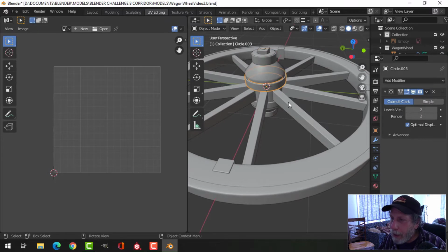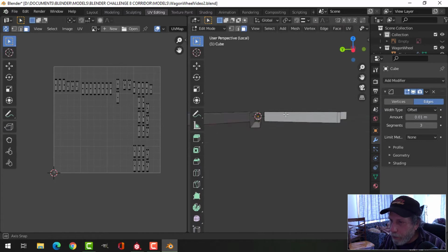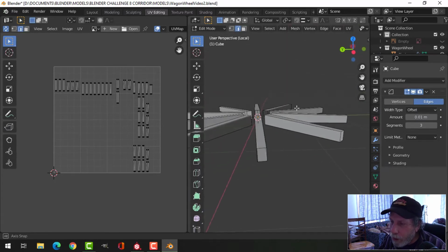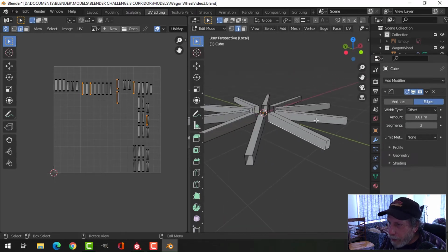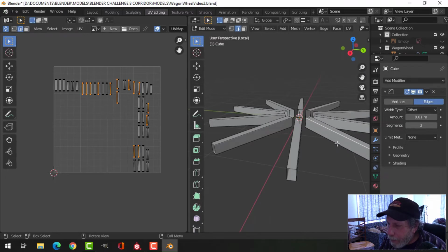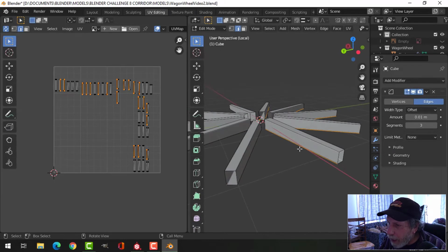Maybe the metal is okay. Let's just come into this stuff and see what we can do. What if we were to come in, and because there's nothing on the ends, if I want to unwrap this like it's a present, like this is wrapping paper, right? If we take our scissors and we cut along there, okay, we can then just unfold it. So what if I select, holding down shift, select this edge in all of them? Now, maybe it's a better idea to make one, unwrap it, and then copy it a bunch of times, but hey. Okay, Control E, mark seam.